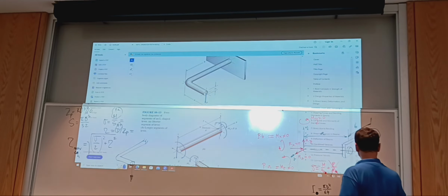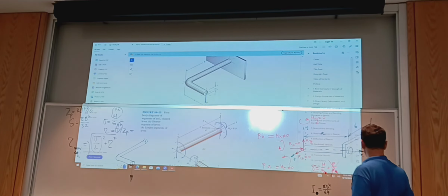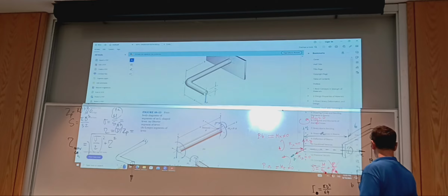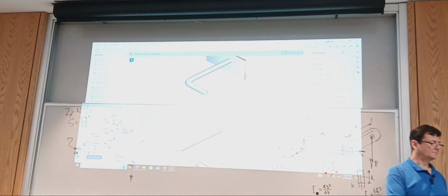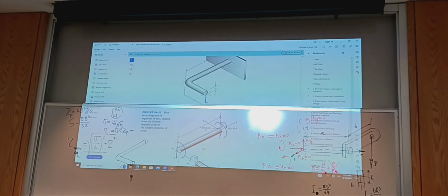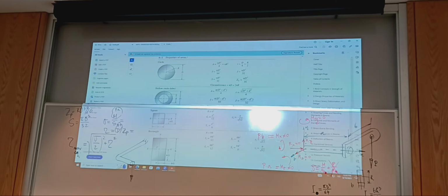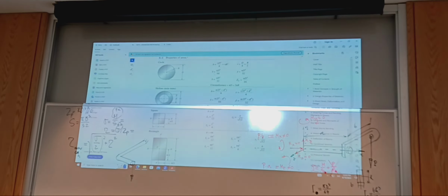If we call this H, and if we call this B, we have B H to the power 3 over 12. Before you invest into doing these analyses, let's confirm we got it right. As for this one, it'll be Ix, in our case, B H to the power 3 over 12. So we did something like this.